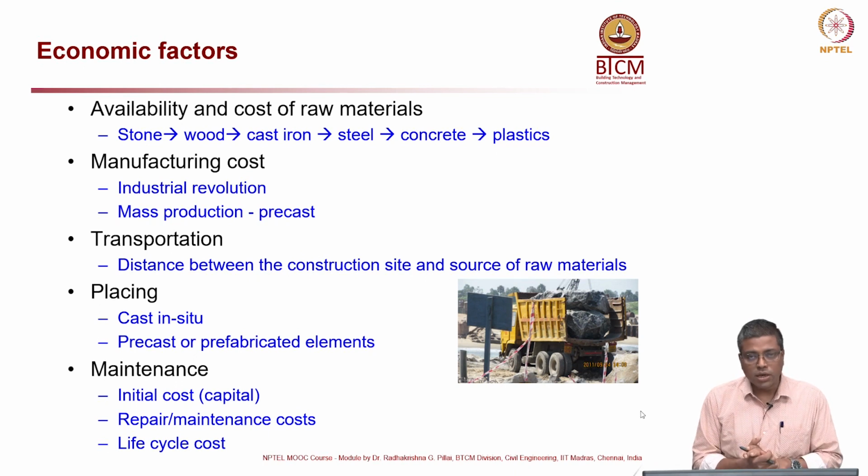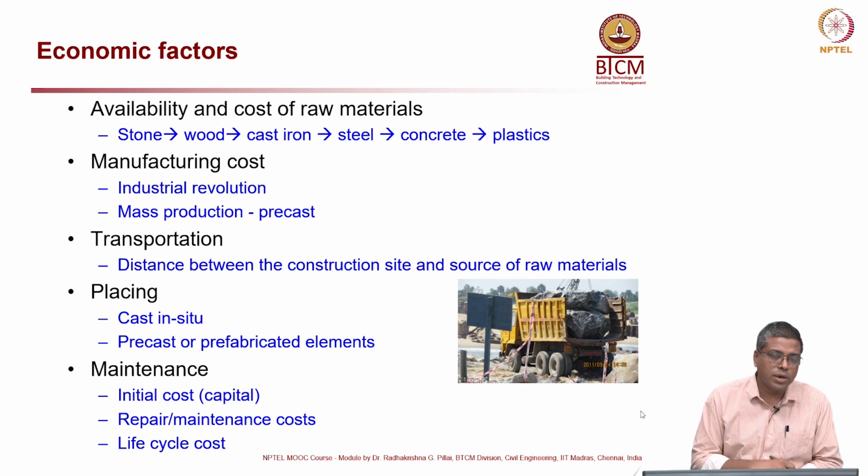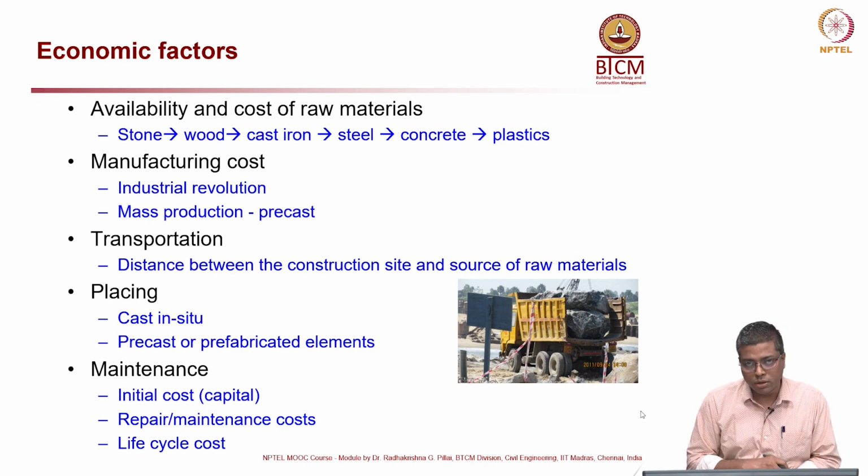That technology is picking up very fast, and it is the need of the hour, because there is a huge requirement of construction in our country. So, precast construction technology is very much essential, I would say. Sometimes precast may not be possible because you cannot transport the precast elements to the particular site. In such cases you might have to go with the cast in situ option.